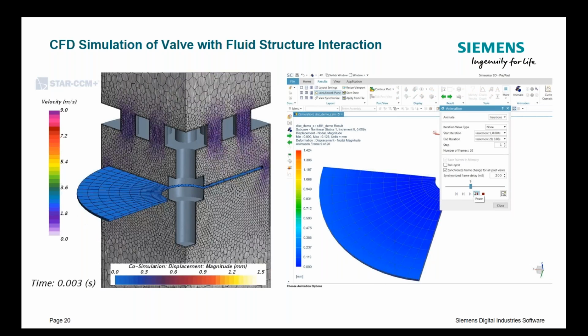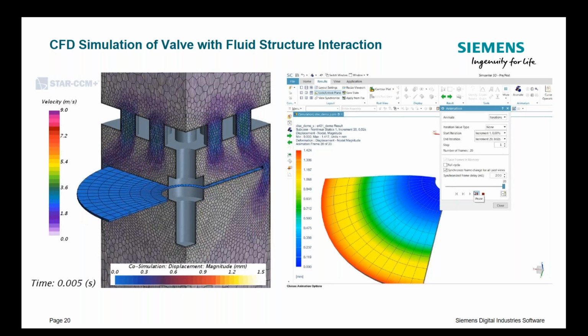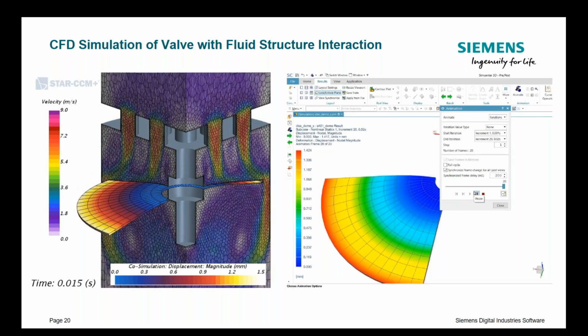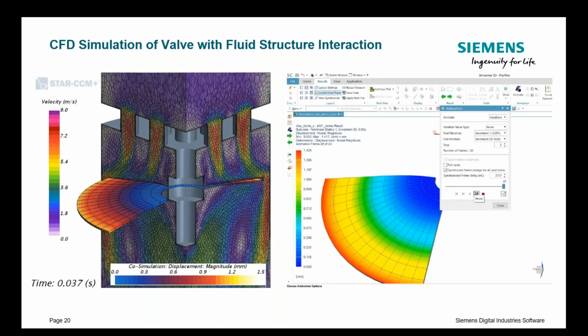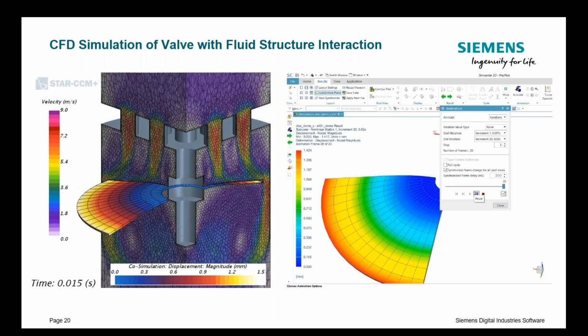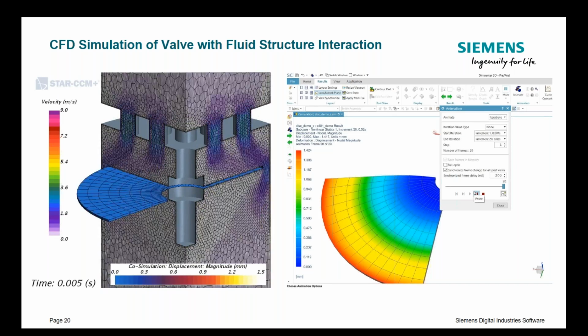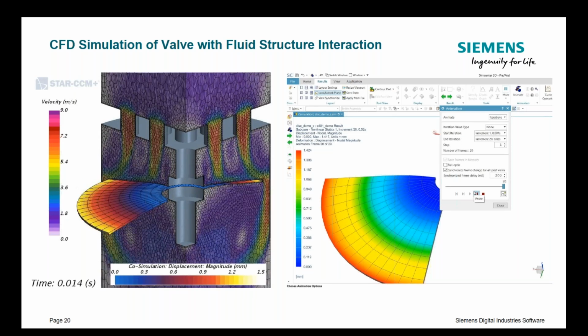And co-simulation to achieve fluid structure interaction for complex flow-induced large deformations. In this case, we're simulating a heart valve element. But fluid structure interaction is important, particularly because without it, you don't know the loads on your structure, and if you don't know, you'll have to estimate. And estimations often lead to uncertainty and conservative designs, which are heavy and less competitive. So being able to accurately predict fluid structure interaction allows you to design safe, competitive, and lightweight components.